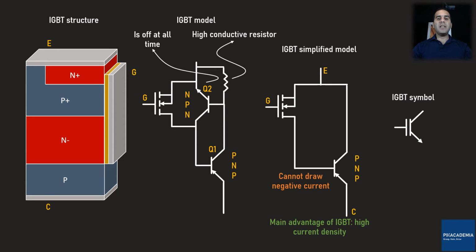For turning the IGBT off, all we can do is to turn off the MOSFET, so the base current gets to zero. Then we need to wait for the recombination of the charge carriers in the BJT before the device turns off. As a result, we will observe the tailing current in IGBTs at the turn-off moment.